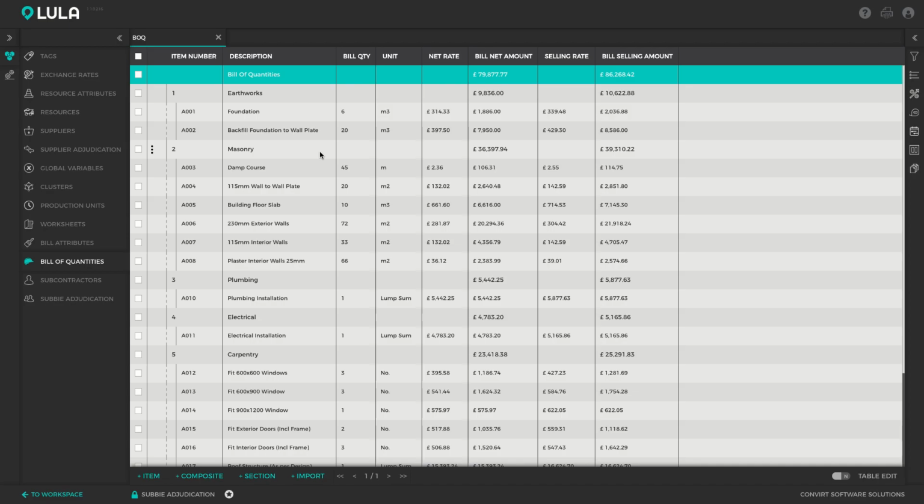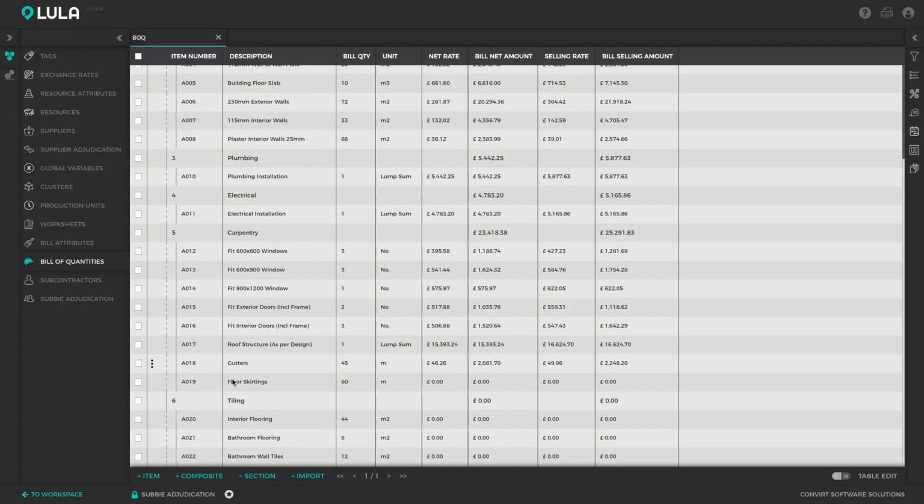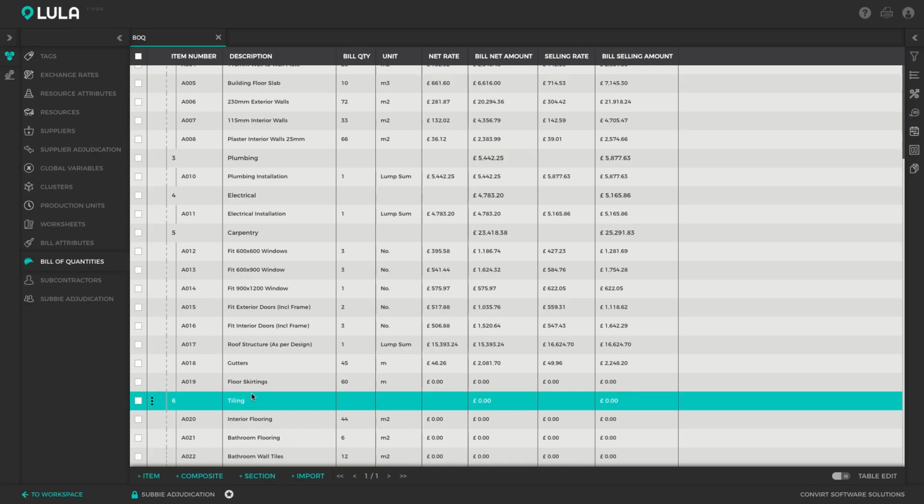Hi everyone, in today's video I'm going to show you how to work with Lula Build's Subbie adjudication module. When pricing a tender, it is quite common to subcontract certain portions or trades in a project. Something like tiling might, for example, be subcontracted out, and you might typically ask a few different subcontractors for quotes, and it's then convenient to have a way to compare these quotes to see which subcontractor is the cheapest, and then to commit that subcontractor's rate to your bill of quantities.